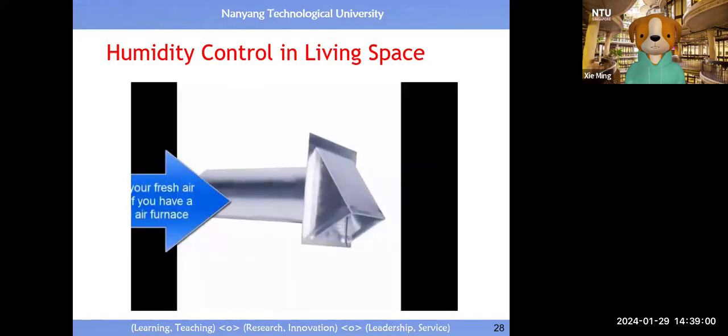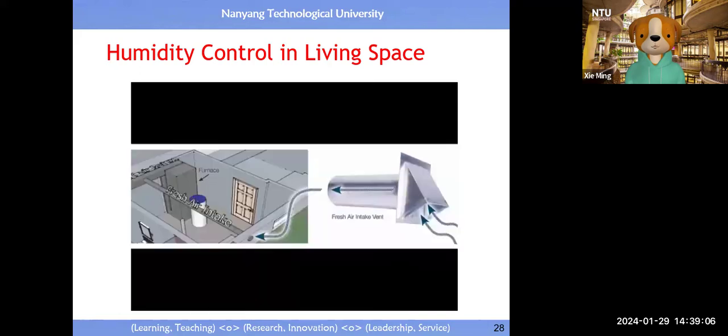If you have a forced air furnace, check to see if you have a fresh air intake. Fresh air intakes make all the difference in reducing indoor humidity in the winter, providing that they are working properly. These units often require seasonal cleaning and should be located where good quality air can be drawn into the home.